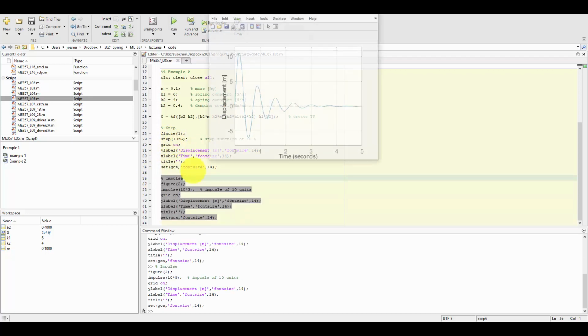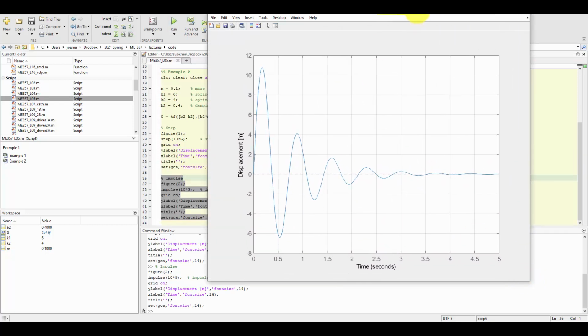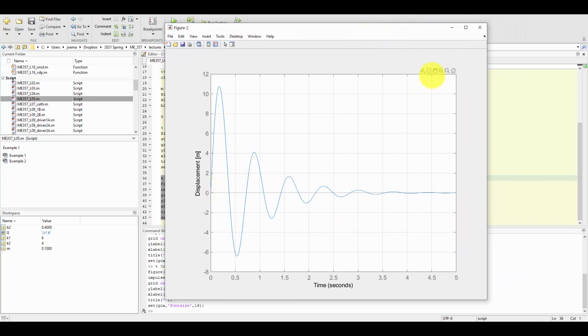All right, so basically at time 0, we smack it with a hammer and then we let go and see what happens to it. So at time 0, we hit it with the hammer and we see that it goes down to an amplitude below the horizontal, 10.8. Now again, the magnitudes of the step and the impulse don't really align because they are different types of units here, but we still see it goes below the equilibrium point, it goes vertically downward.